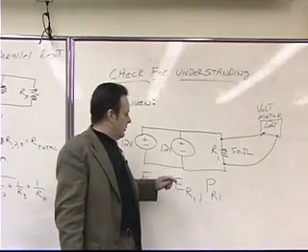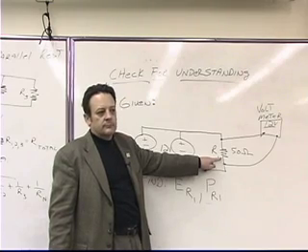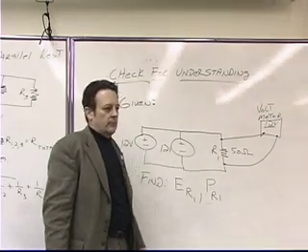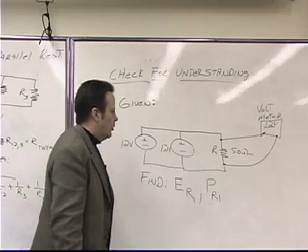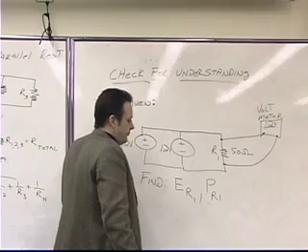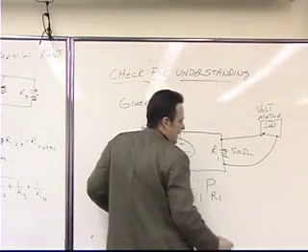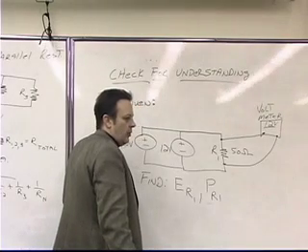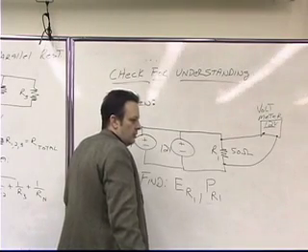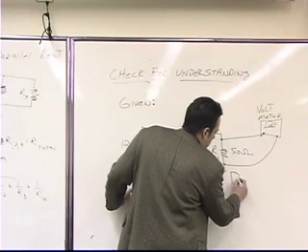Now, what about the power that's being dissipated on this resistor right here? We got 2.88 watts. Okay, what formula did you use? We used E over R. E over R for power? No, E over R equals I. And I times E.